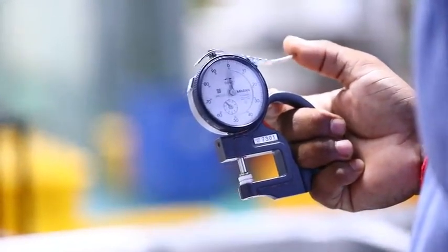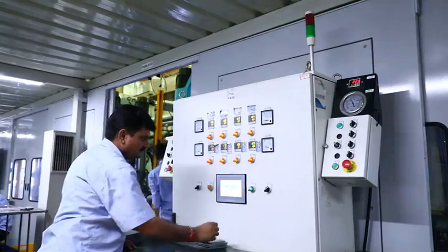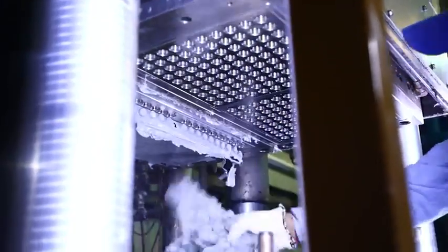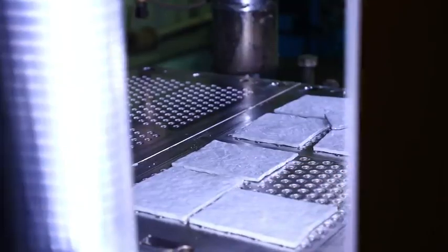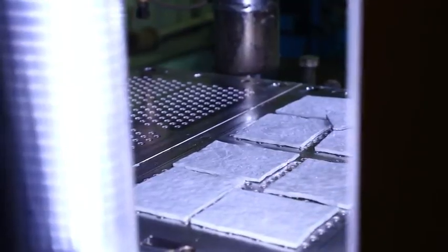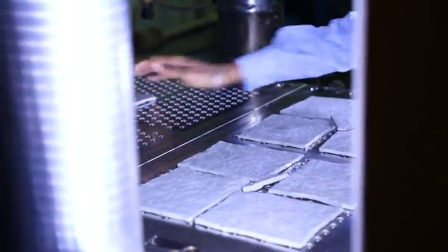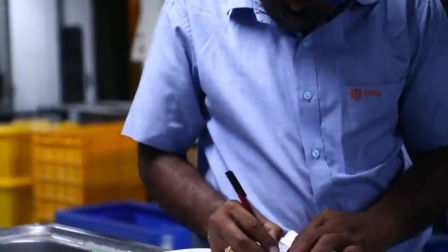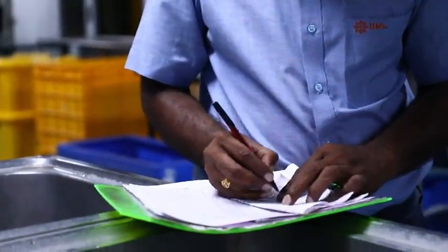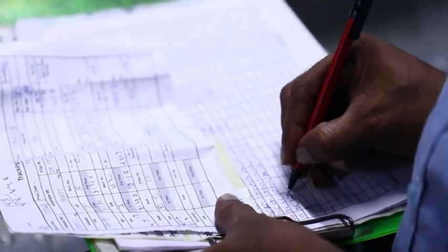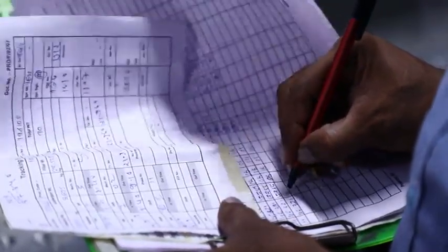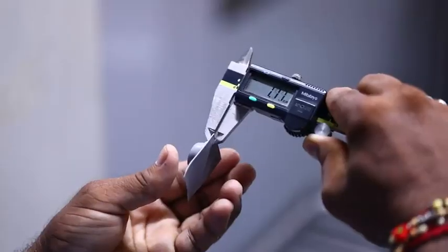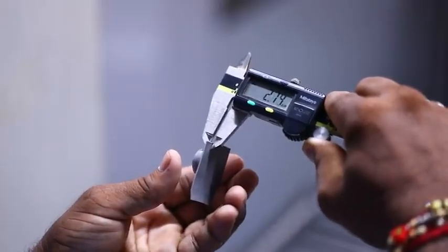The function of in-process controls is monitoring and, if necessary, adaptation of the manufacturing process in order to comply with the specifications. In a typical case, the dimensions of a sample unit of the produced rubber caps are measured using a vernier caliper. The dimensions are recorded in a sheet. The dimensions and other physical attributes are checked and the observations are recorded in the IPQA records. The deviations are then studied and the reasons for deviation are corrected.